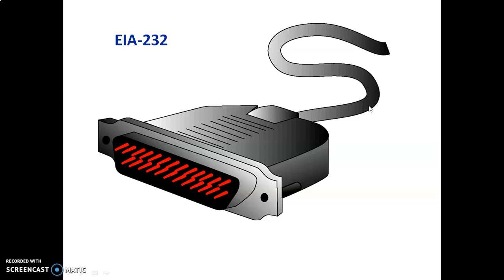That's about 50 feet. A DB25 connector is a plug with 25 pins or receptacles, each of which is attached to a single wire, each with a specific function. The term male connector refers to a plug with each wire in the cable connected to a pin. The term female connector refers to a receptacle with each wire in the cable connected to a metal tube or sheath. In the DB25 connector, these pins and tubes are arranged in two rows, with 13 on the top and 12 on the bottom.